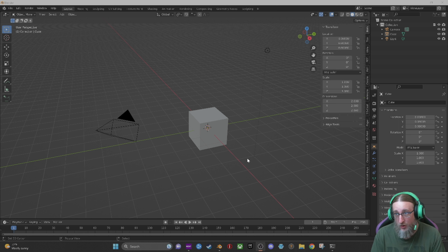After that, you want to click on New for the texture here. And then if you go over all the way to the end, you'll see these two little bars. You click on that, it'll bring you over to the texture panel here. You could also just click down here if you want to, but for me, it's easier. You're in the modifier panel and you just click New and then over there.